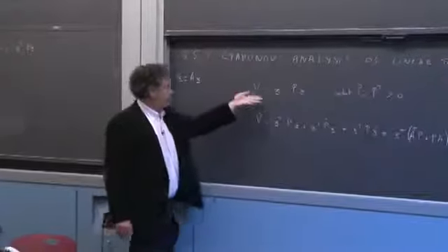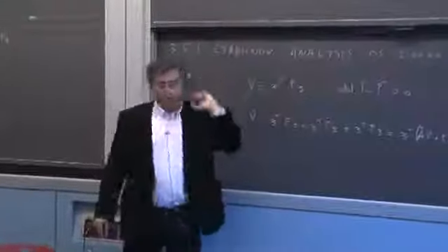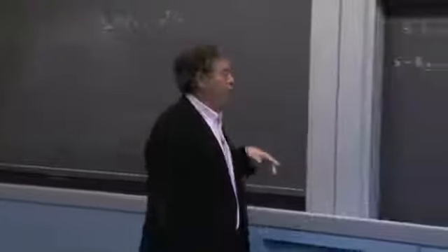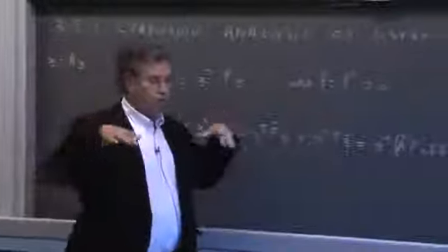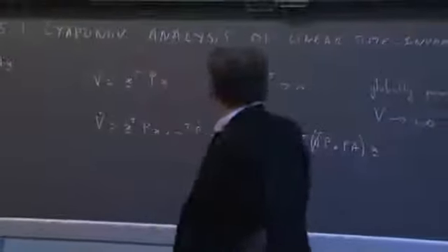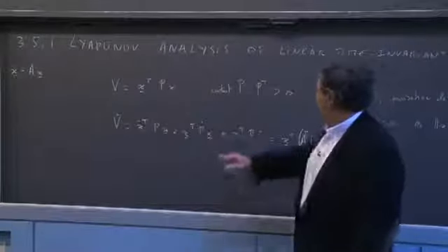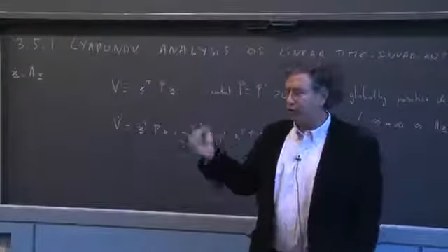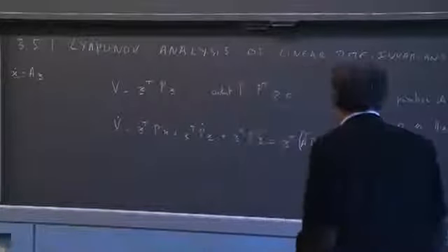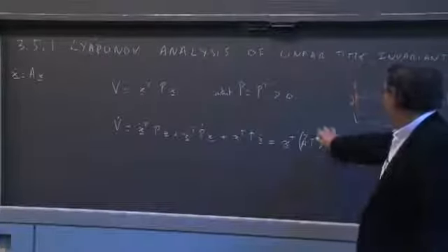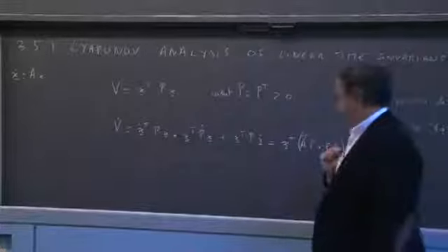Okay? So at this point, we have our linear, strictly stable system. We've taken a guess at what the Lyapunov function candidate could be. We picked a quadratic form, perhaps motivated by things like LQ or something like that, but anyway, that was the guess. We differentiated the product, so we get three terms, and we replace x dot by Ax, and we get this.